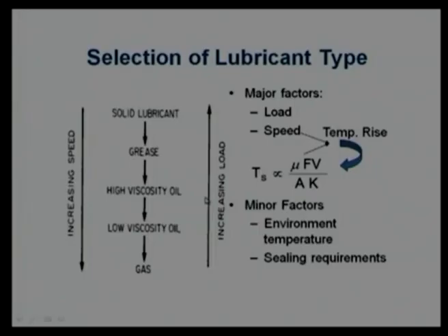So, it is slightly complex. With more load, we should choose semi-solid and solids, but that is going to increase the temperature. If the increase in temperature is reducing the viscosity of the lubricant, then we should choose some sort of additives. And this indicates that a study of the additives along with this kind of lubricant is essential.